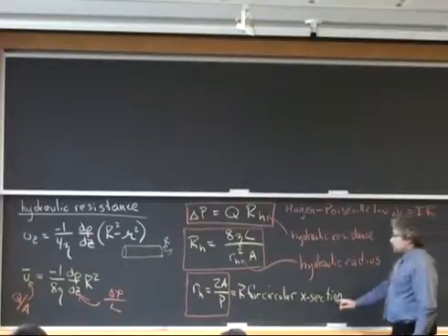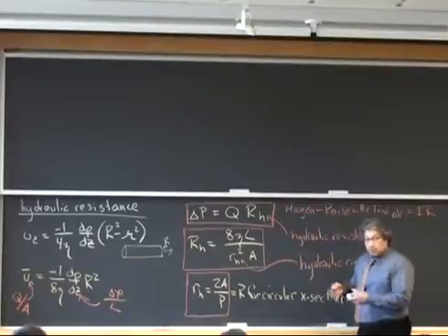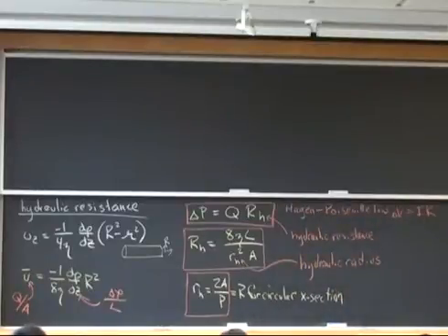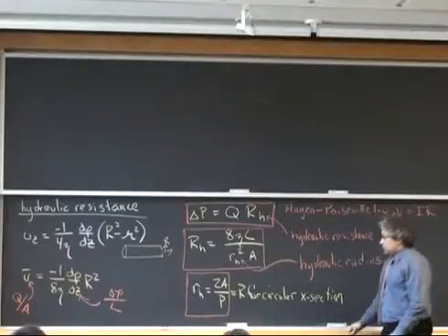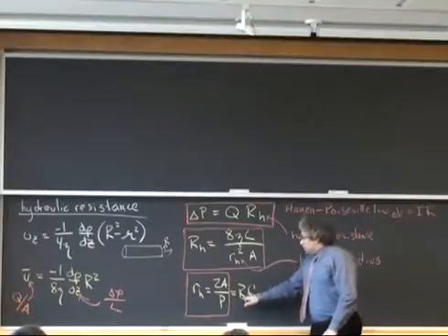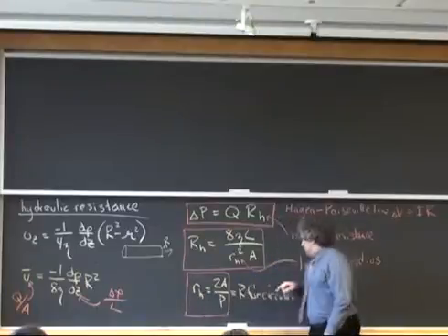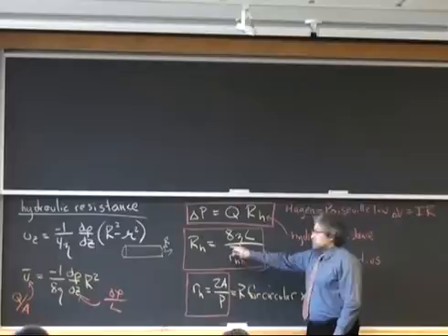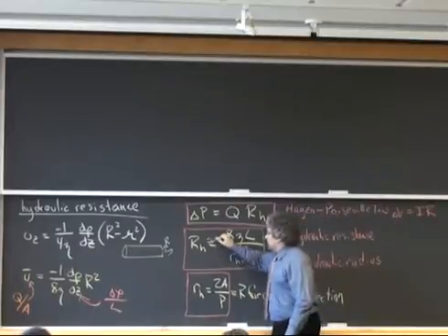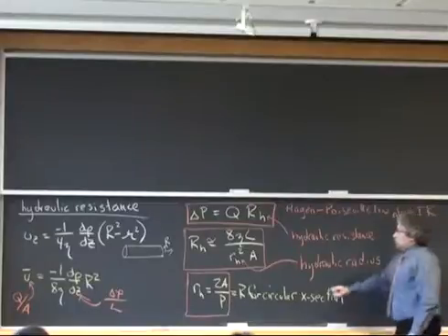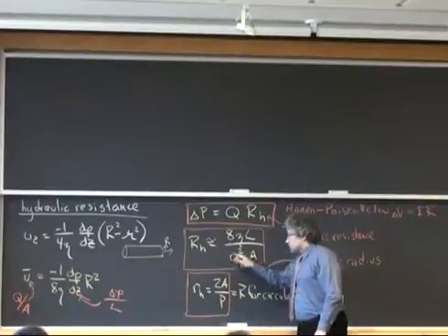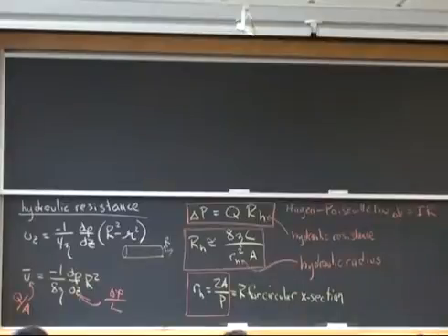In fact, if we have any other cross-section, as we would typically expect to get if we were doing any sort of real microfab, or at least any sort of plasma-based etching microfab, we're not really going to have a circular cross-section. We'll have something that's more often square or trapezoidal or rectangular. We won't be able to define a radius. We'll have to use a hydraulic radius. And this expression, which before was an equality, now really just becomes an approximate equality. And as a rough rule of thumb, as long as your shape isn't too crazy, we expect that this approximate relation with this hydraulic radius to be good to within about 20% error.